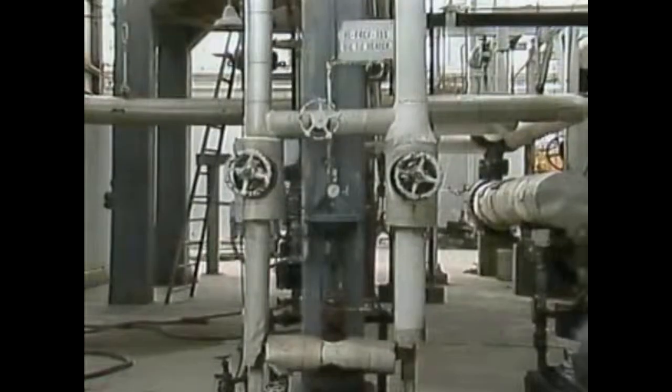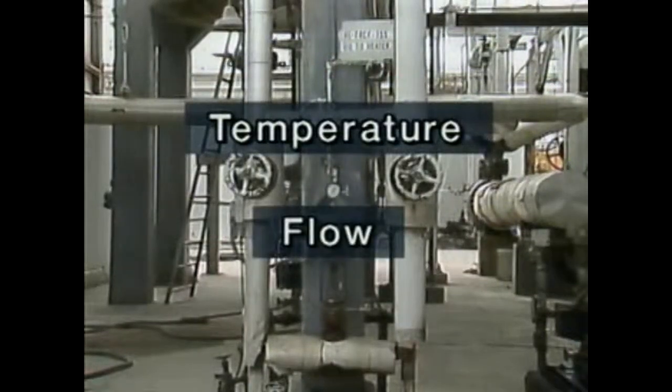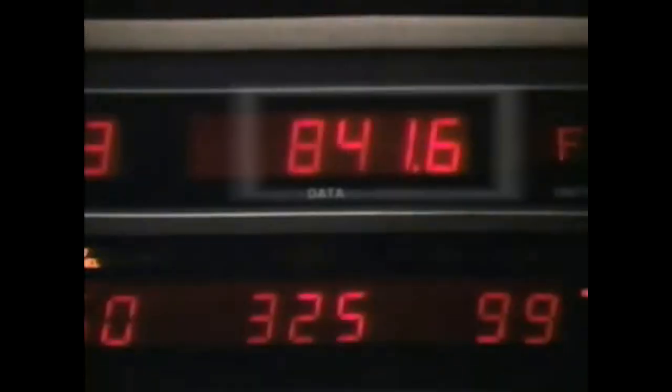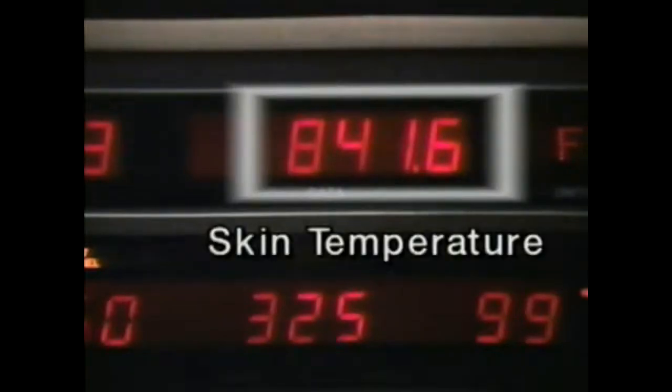Two main variables associated with the process fluid system are temperature and flow. The outlet temperature, in a sense, is the most important furnace temperature reading, since the main function of the furnace is to heat the process fluid to a certain temperature. Another temperature that's routinely checked is the tube metal temperature, or skin temperature. Overheated tubes can lead to tube ruptures and other problems.